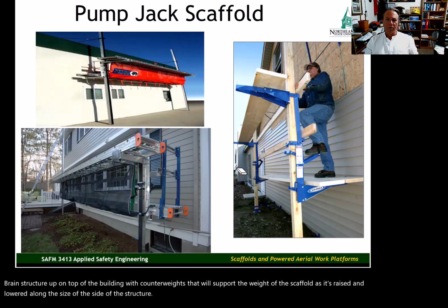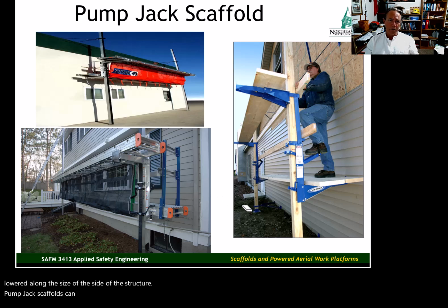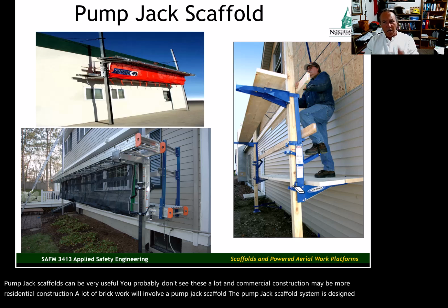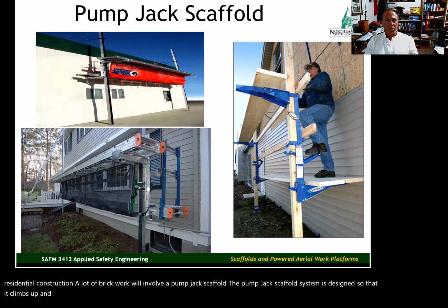Pump jack scaffolds can be very useful. You probably don't see these a lot in commercial construction, maybe more residential construction. A lot of brickwork will involve a pump jack scaffold. The pump jack scaffold system is designed so that it climbs up and down the support structure.